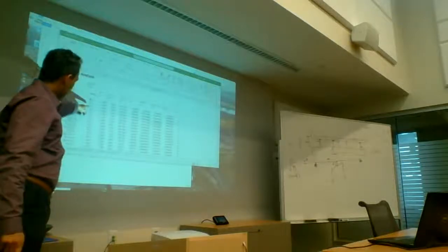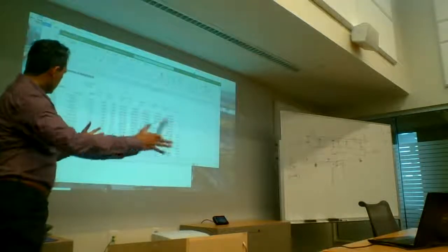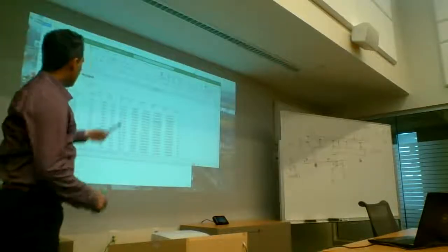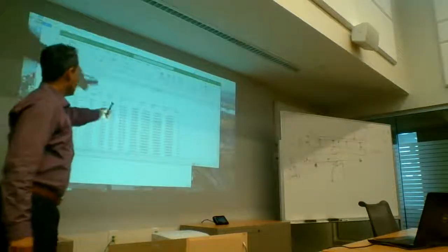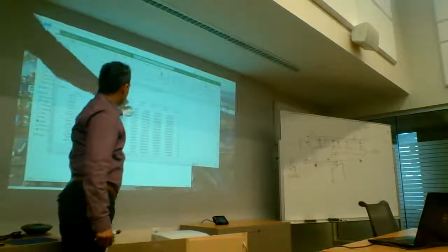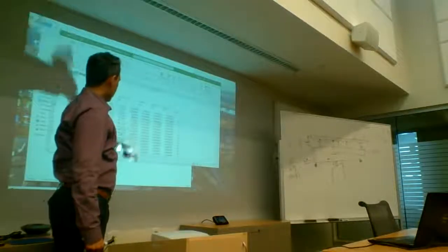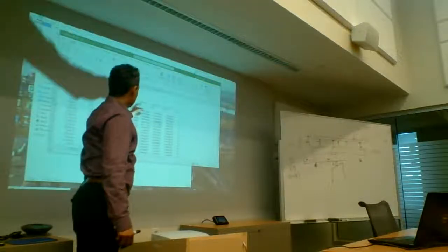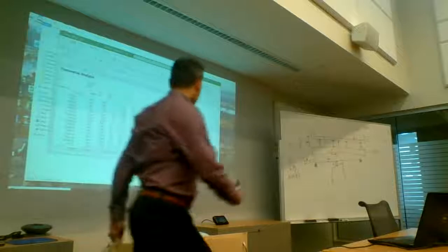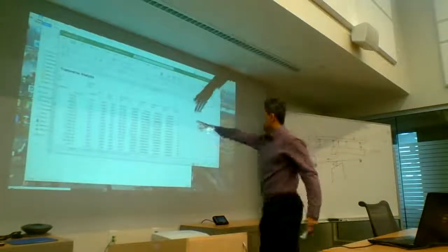I know what section I have at each one of those mid sections, the length of it, the weight of it. Then I multiply Wx with dx, so that's just being multiplied to get the weight. I get Vsx, which is given here based on the formula, Vsx dx, Wx Vsx dx, and then the square of that, and then out comes this Pe.